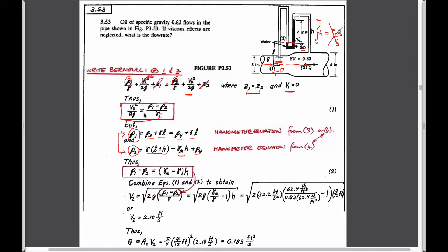We have a velocity defined in terms of those pressures, and so all that remains is for us to substitute into here and to be cognizant of the fact that we have both a gauge fluid, which is mercury, and a fluid in the pipes, which is not mercury. So we have gasoline flowing in the pipes. I guess it probably would be some oil, right, because it's lighter than water. And so if we substitute these pressures into here, we can solve for the rest of it.